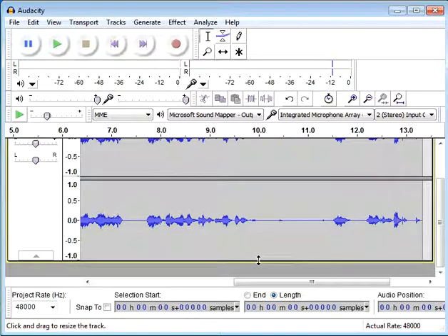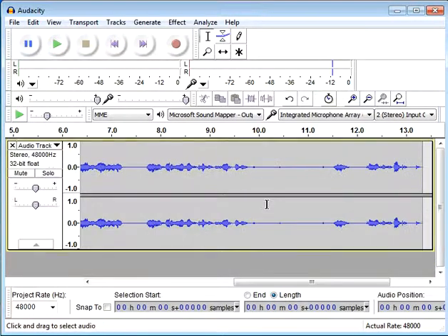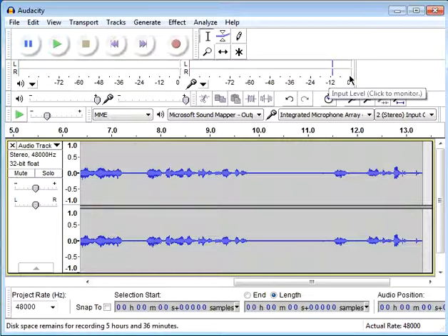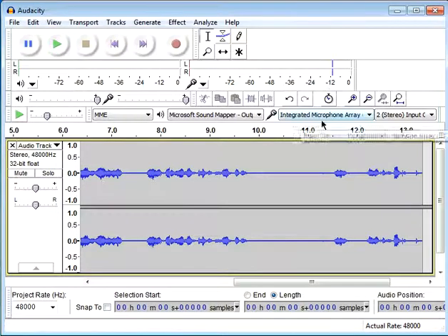Now you may have noticed also that I'm recording on a very low resolution screen to make it easier to see the video. So I'll just now enlarge this window, and here you can see the voice levels. It's saying it's recorded to something like minus 11 dB, that's minus 6. Minus 6 is half the amplitude, 0.5, and 0.25 will be about minus 12, and there's probably a peak somewhere that's just gone above that level.